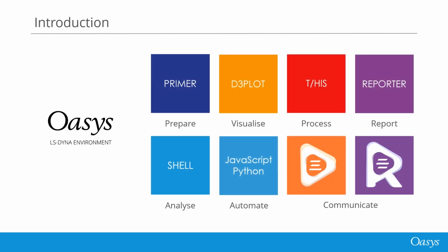These features are aimed at all CAE engineers using LS-DYNA. So before starting, I would like to give a brief introduction to Oasys D3PLOT. Oasys D3PLOT is an advanced 3D visualization package for post-processing Ansys LS-DYNA analysis results. It allows users to animate analysis results and to extract or derive over 100 data components from LS-DYNA output. The visualization is achieved with advanced graphics, including control over shading, contouring, lighting, and transparency.